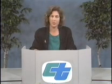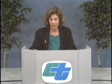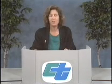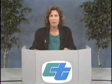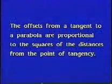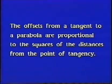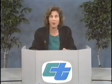Field applications of vertical alignments usually require that elevations be calculated for specific stations or at regular intervals. These values may be derived by either the tangent offset method or the parabolic curve equation. Both methods are based on the following properties. The offsets from a tangent to a parabola are proportional to the squares of the distances from the point of tangency. This presentation will only discuss the parabolic curve equation.